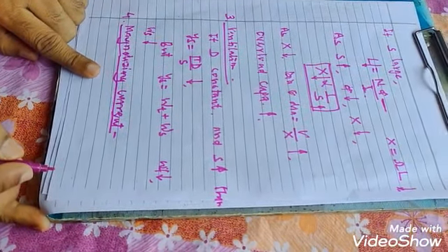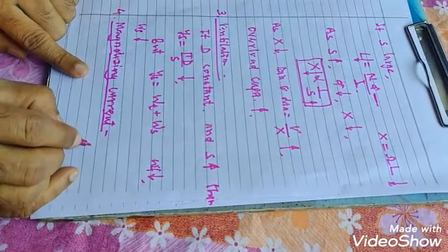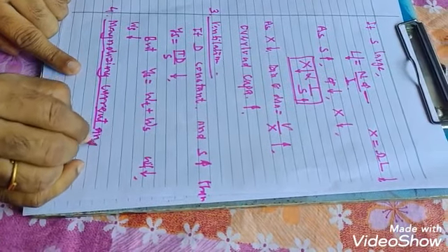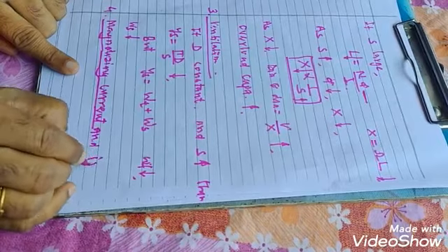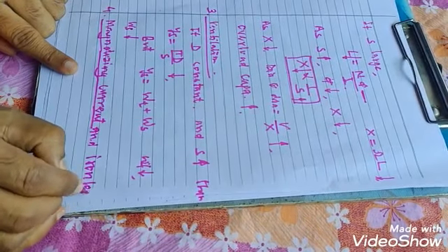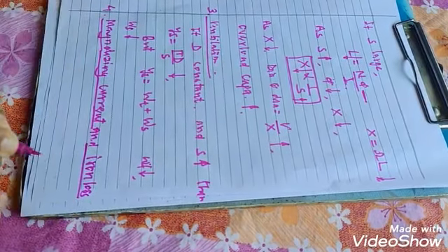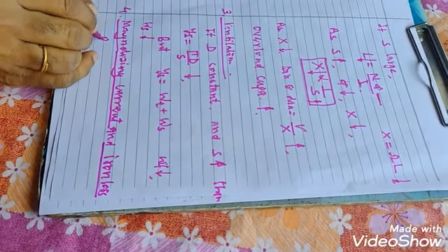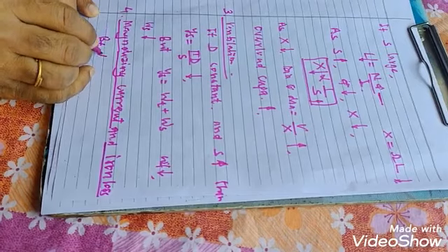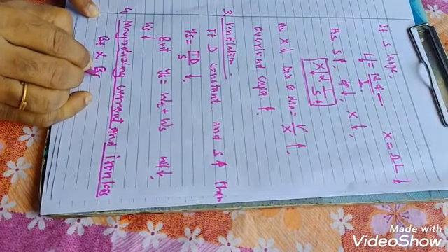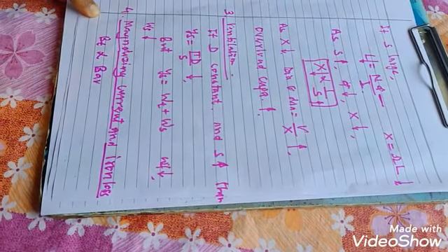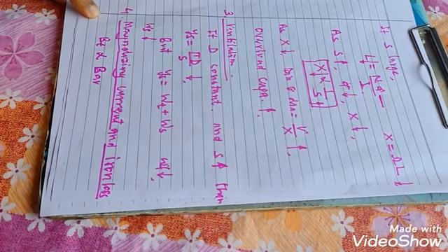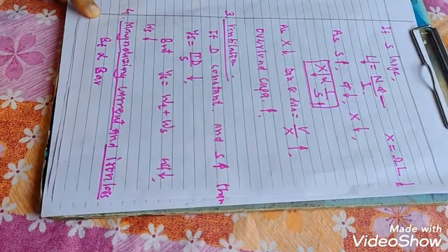Magnetizing current and iron loss. We know the flux density in teeth is directly proportional to B average, which is the specific magnetic loading.